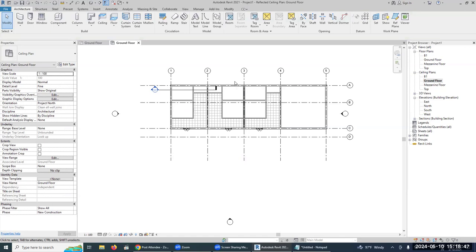Go to the ceiling plan, cross selections. Select it in a cross selection. Only keep the ceiling in the selections and then mirror. You are in the ceiling plan, correct? Then mirror. There is no identical in place. This will double count in the schedule. I think something is wrong.